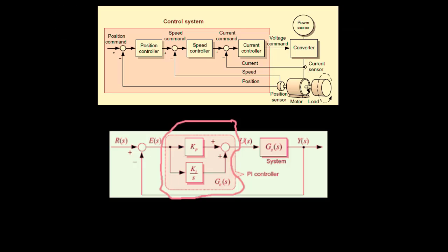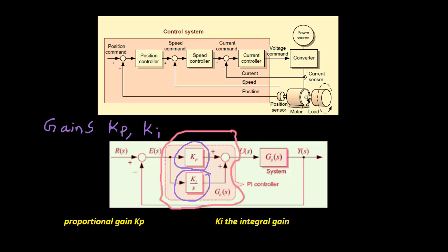The PI controller has been widely used in motor drive systems as the controller for the current, speed, or flux linkage control, because it could give a satisfactory performance. The performance of the PI controller depends heavily on its selected gains. Thus, it is very important to select appropriate gains of the PI controller for obtaining a satisfactory performance in a given system.